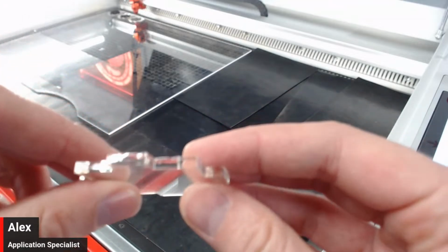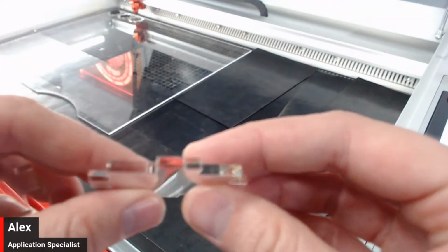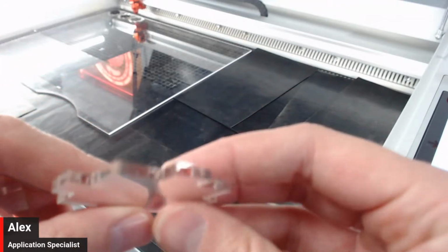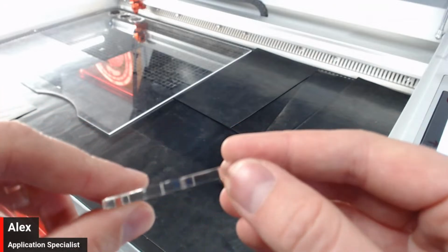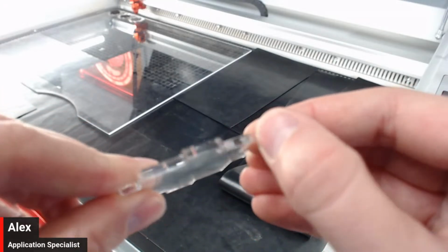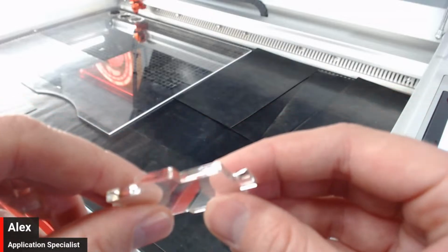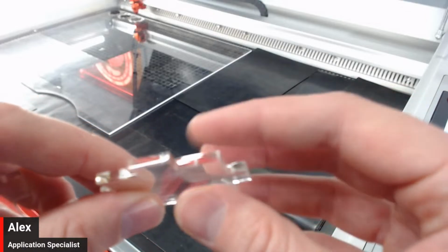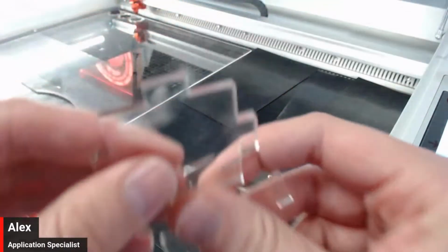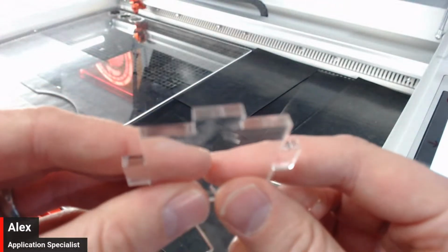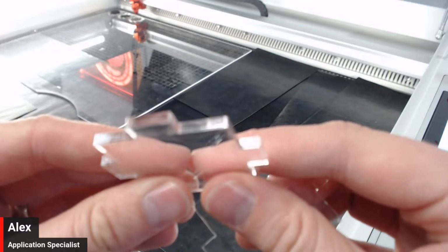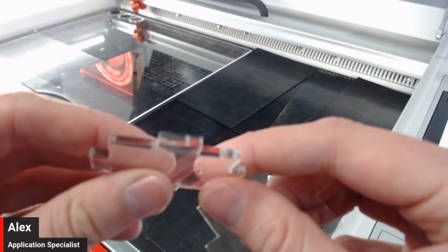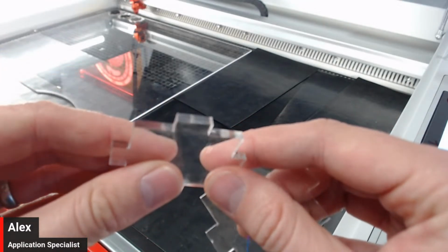But the problem is, this is great if you need that super smooth edge, but what you can find is that you obviously run the risk of more chance of flaming when you cut something with a setting like this versus the slightly faster setting, which I guess on here, to be honest, looks pretty similar, but to me at least I can see there's a lot more visible tiny slight ridges.